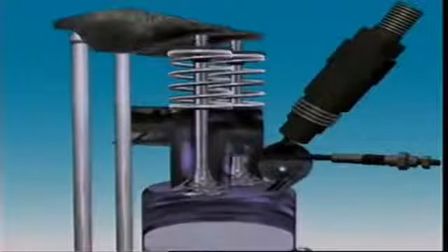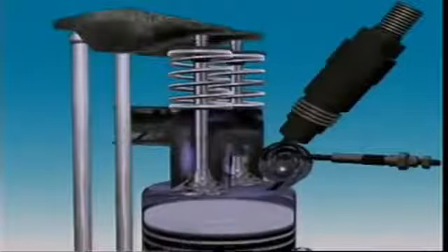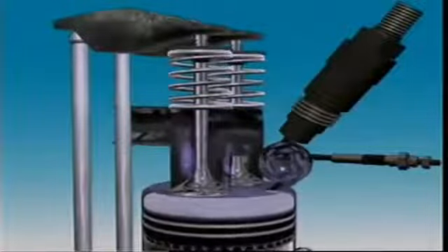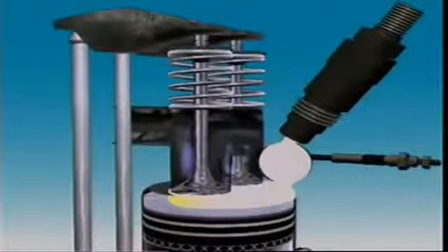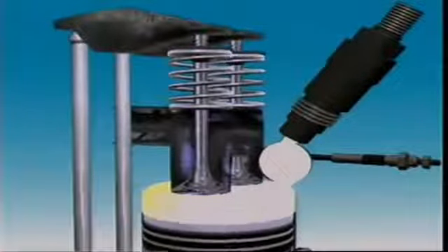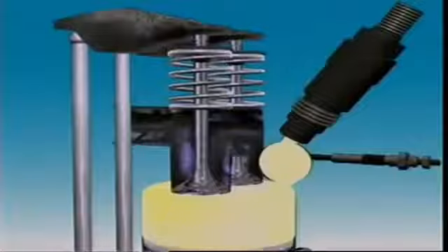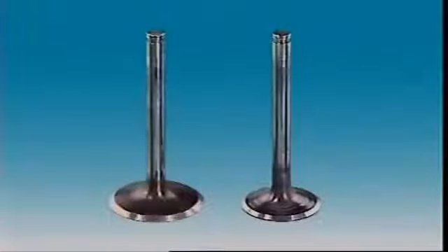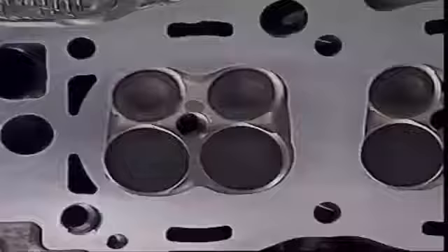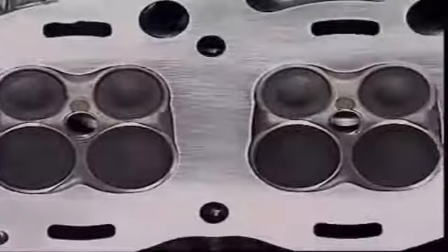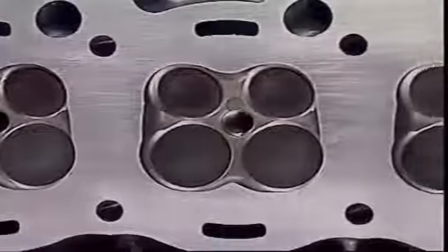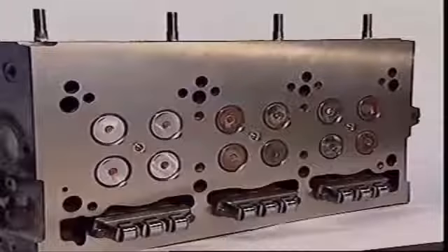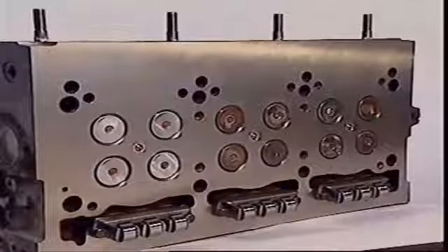Diesel engines are different. Their power and speeds are controlled by the amount of fuel injected, so it isn't necessary to control airflow into the intake manifold. Almost all four-stroke petrol and diesel engines use valves, which are located in the cylinder head. This is also true for two-stroke diesel engines that are used in road vehicles.